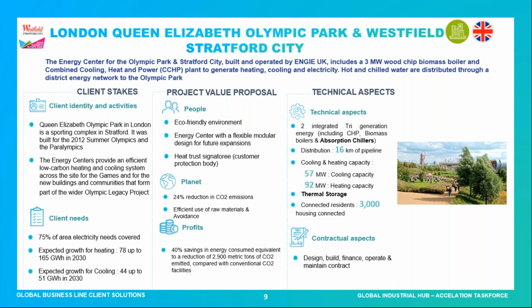And you can see the capacity installed for each of the facilities, cooling and heating. In that case, we are using biomass in order to produce heat. And while we are producing heat, we are benefiting from the excess heat to produce chilled water thanks to absorption chillers. In addition, we are using thermal storage. But the specificity of that contract is that we are already in the frame of what we call sector coupling: generating power, producing heat, and producing cold.